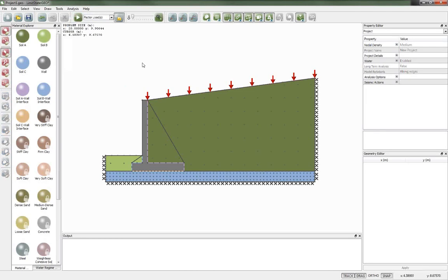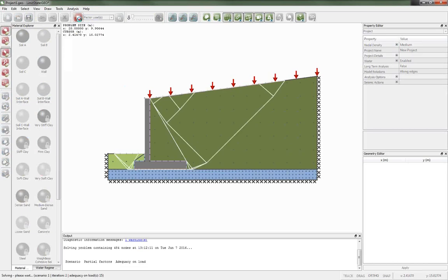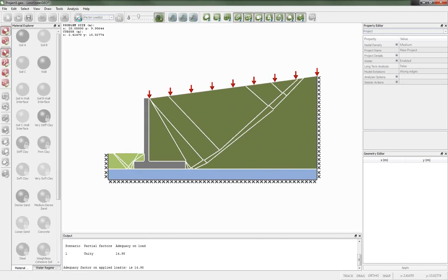And you see I get even more nodes there. And that's just to help the software. In this particular case, because we're underneath the foundation, we might get a squeezing failure. The software puts that in.